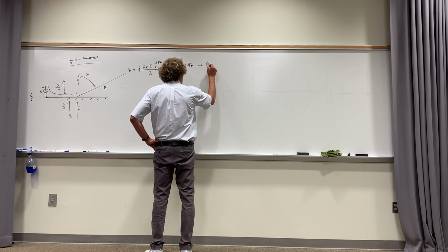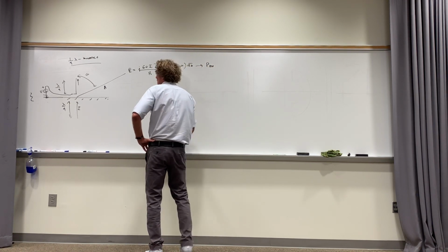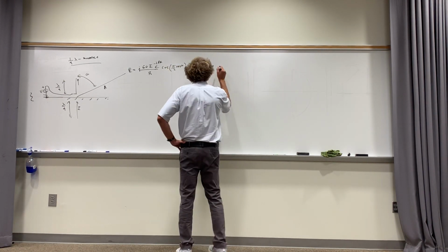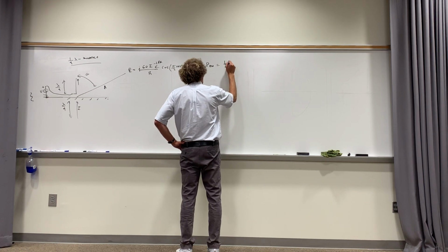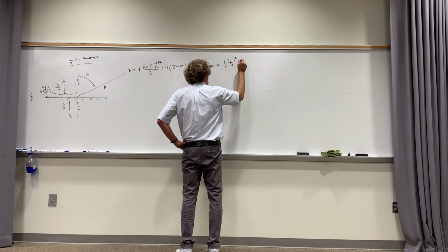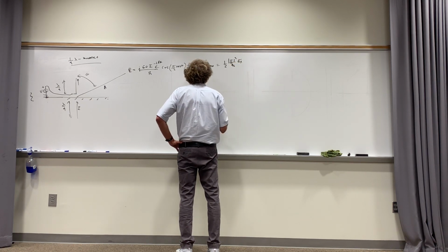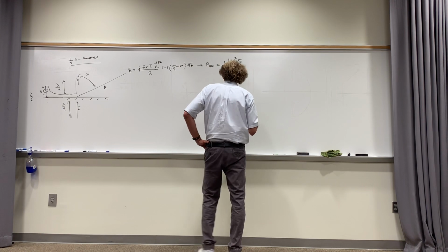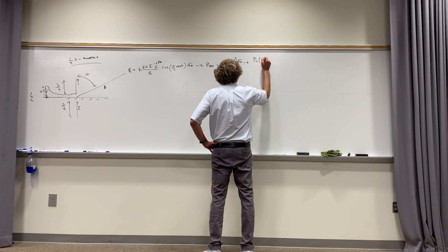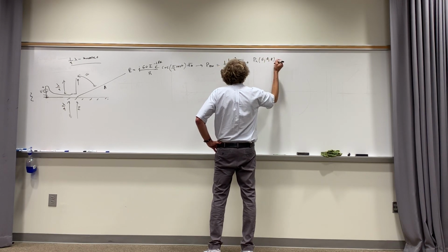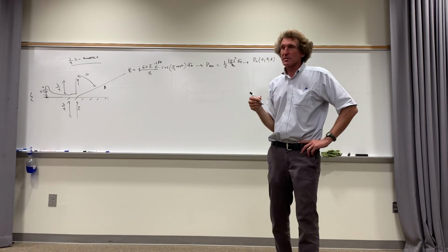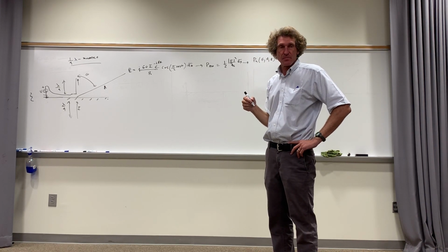That means the P-Av would be the same as the half-wave dipole, correct, class? P-Av would just be equal to, I'm not going to calculate it exactly, 1/2 times the magnitude of the E field squared over eta naught, in the a r direction. So P-Av is the same. Another thing that means is that the normalized power density as a function of theta, phi, and r would be the same as a half-wave dipole. Do we all agree on that? There's a reason this is important. Agreed, class?